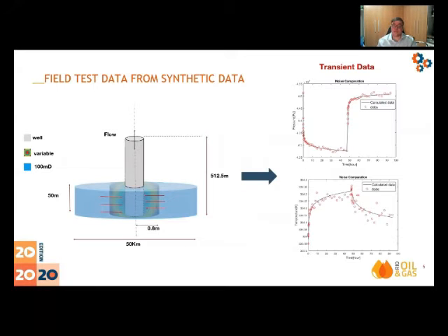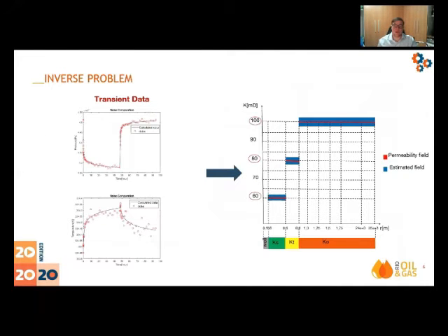In practice, the first part of the project simulates a cylindrical reservoir coupled with a wellbore, with heterogeneous permeability near the well, to provide the pressure and temperature transient data. To simulate the field data, noise was introduced in those simulated data. Given this noisy data, we solve the second part of the project. For this, the ES-MDA method is applied to estimate the values of the permeability of the different regions and the porosity, making a history matching with the pressure or the temperature data.